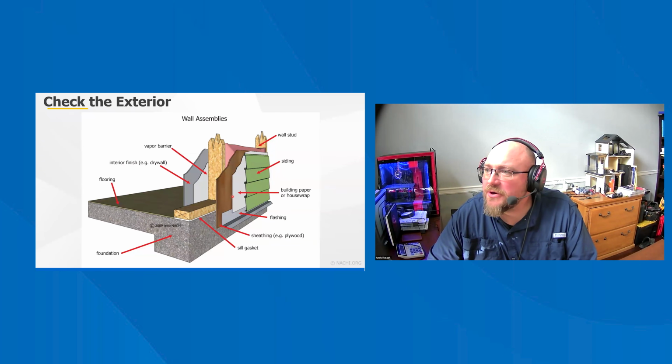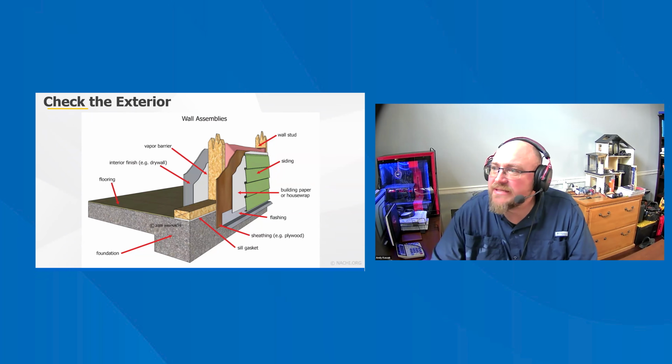Check the exterior. An exterior wall of a building should be properly sealed, protected from moisture, and insulated adequately to increase comfort, reduce noise, and save on energy costs. Exterior walls are one of the most complex systems in a building. A drainage plane in a wall system makes an easy pathway for water to drain away from the house. Rain leaks cause a lot of problems for walls.